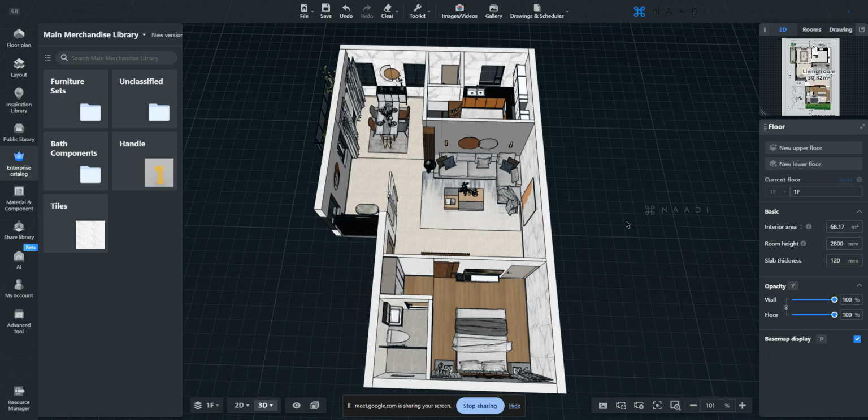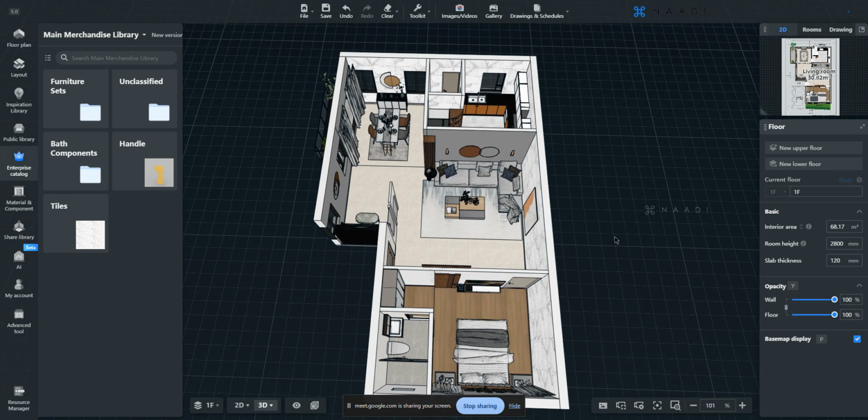Make sure that your entire floor plan is modeled, because I could notice some designers may not design their service area or utility since their major focus is on this region. If that is what you want, that is not an issue, but in your 2Ds you will see that space as empty. But if you want to generate a complete drawing for your entire floor plan, make sure all your spaces are modeled.